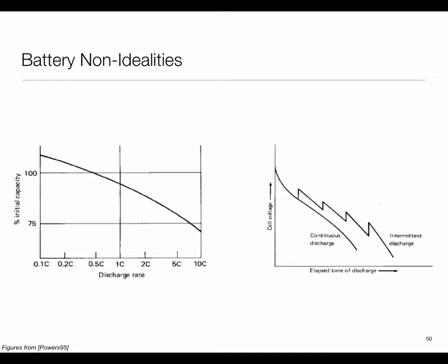So there's a phenomenon in many physical systems called relaxation. Basically there's a recovery effect in the chemical system which happens, which is kind of shown out here. Battery voltage drops, I stop using it, it goes back up, and then again the system apparently runs. So what this suggests is that in embedded systems, one way of getting more juice out of the battery could be to put them into sleep periodically so that the battery relaxes and then you again start. So these are kind of nuances of using batteries more effectively that come up.